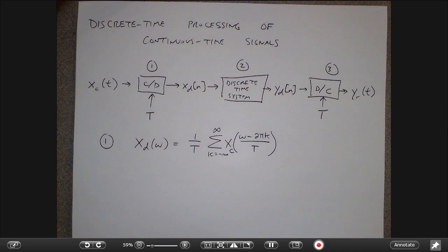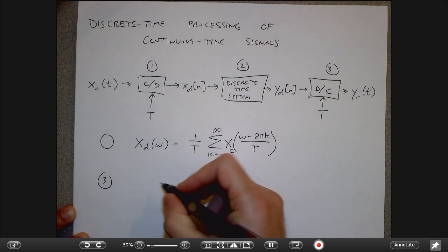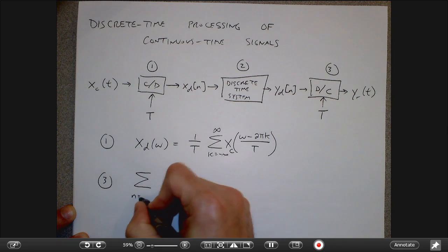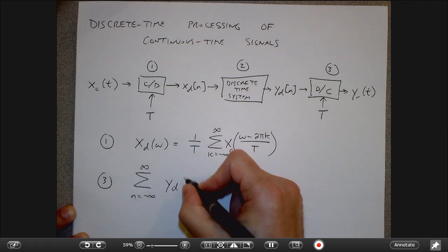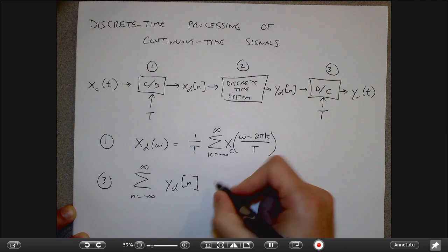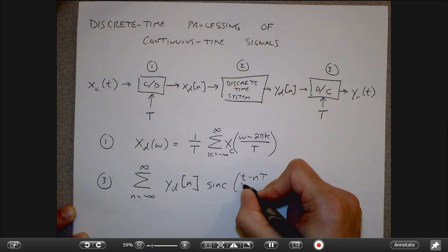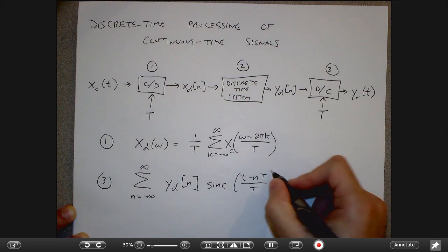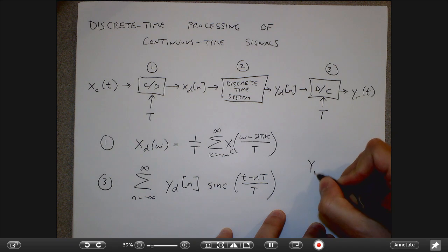They occur every 2 pi places. Then, how do I reconstruct the signal? Well, the reconstruction filter, if I want to go from D to A, is a combination between the original values and a whole bunch of sinc functions.